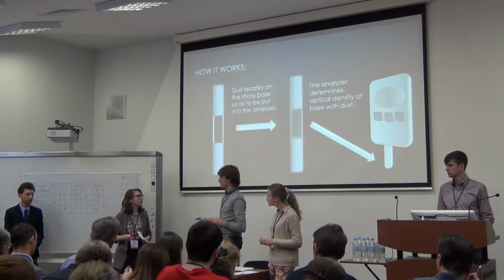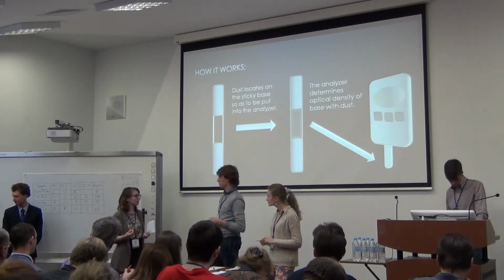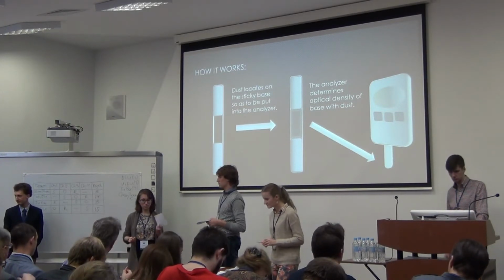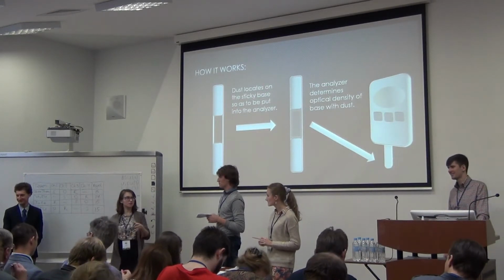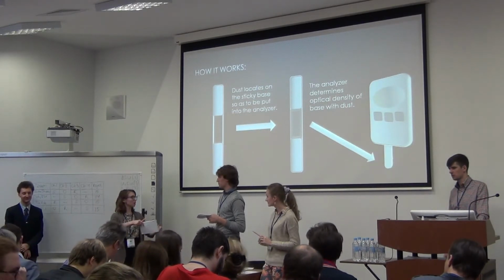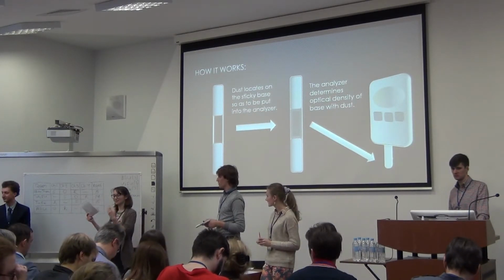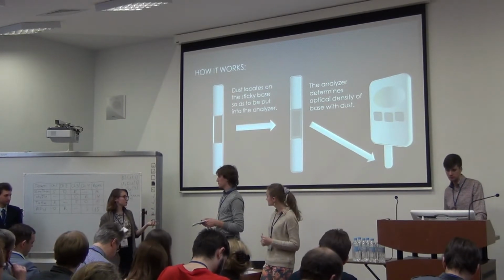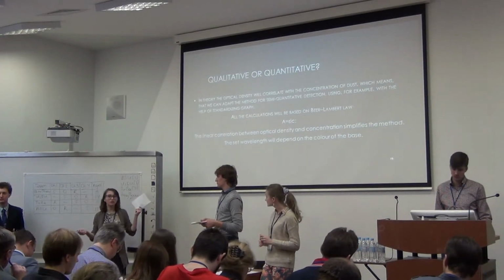But when we speak about the calibration of known concentration, we can produce some dust artificially with known size and known properties, and take that into account to make the linear correlation, because using the Lambert-Beer law, as shown on the slide, we will have the linear correlation.